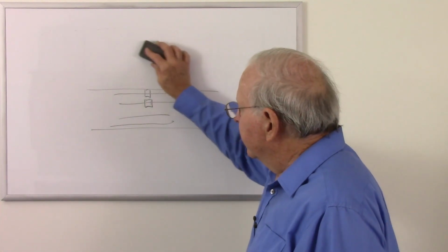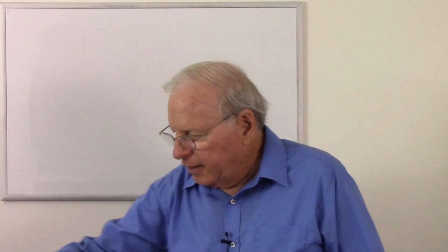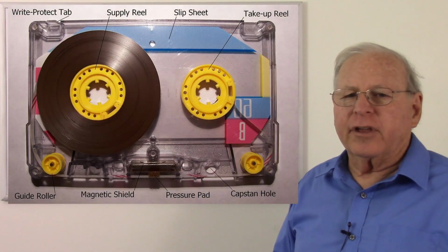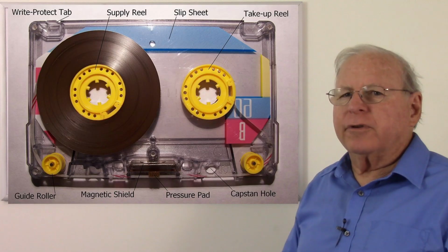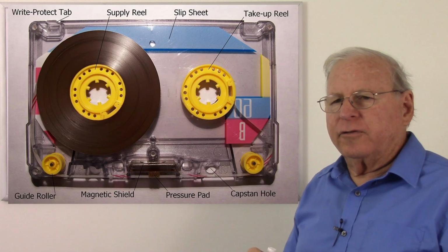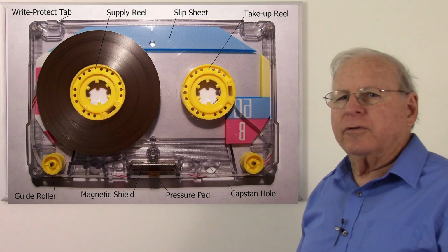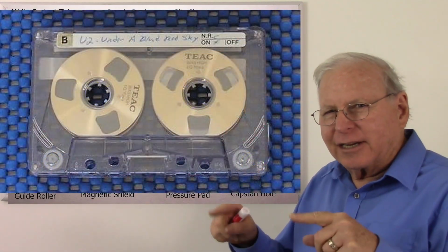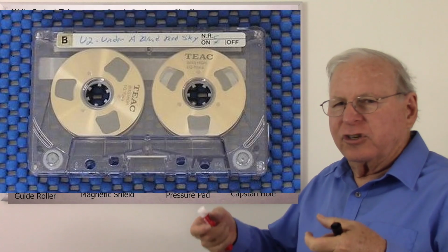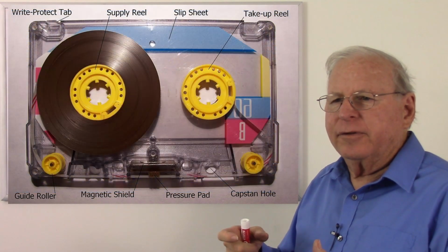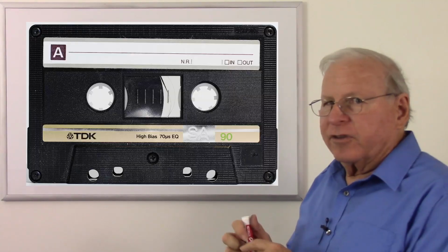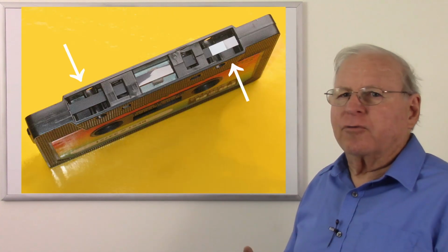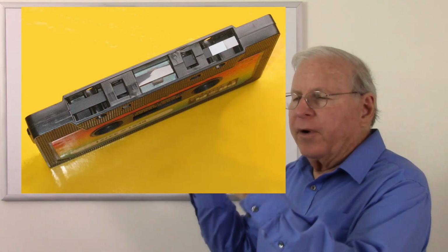And since we're now talking about cassettes, let's talk about how cassette tapes worked. So here's a compact cassette. It's a self-contained cartridge with the tape in it, and it has holes in it to facilitate spindles that come through to move the tape reels. You could get some high-end cassette tapes that actually had little tiny reels in there. Most of them just used the shell of the plastic to keep the tape in place. But there were holes to facilitate the spindles to move the tape reels, and then in the front there were holes to facilitate the capstan, the pinch roller, and the record and erase heads and whatever.